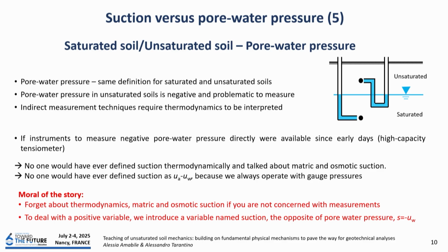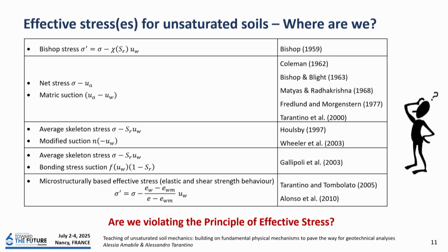So the moral of the story, forget about thermodynamics, matric and osmotic suction, unless you are concerned with the measurement, but it's not the topic that you are dealing with at undergraduate level. And simply, we introduce something that is named suction. By convenience, it is the opposite of the pore water pressure in order to deal with a positive variable. Then you go to the effective stresses.